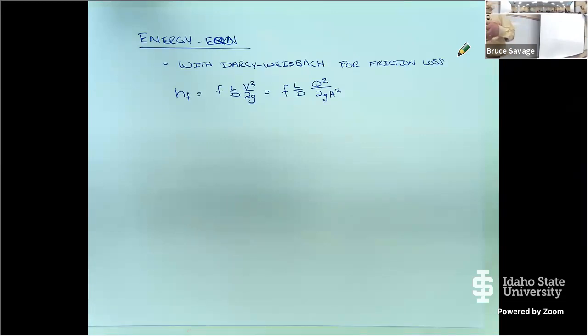It is dimensionally homogeneous, whereas the Hazen-Williams has that correction coefficient, or the conversion coefficient. So this one is better, in my opinion, just because it's founded on those physics principles, and it works really well, with the exception, and this is true for the Hazen-Williams as well, of large diameter pipes. Have I told you guys about large diameter pipes? I don't think I did. How it doesn't apply as well.